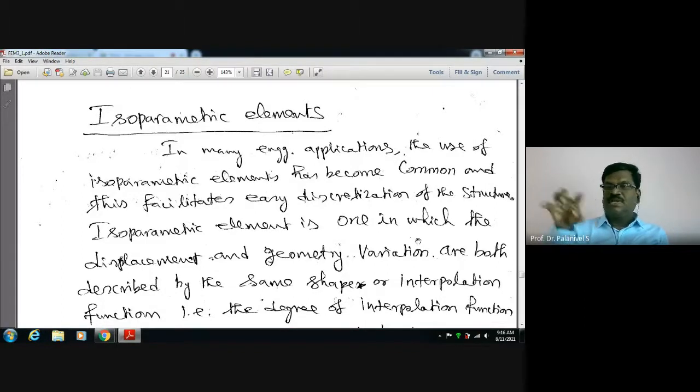For example, you take a triangular element, right? The nodes, you have three nodes, no? Say the displacement at node 1 is U1, V1. Because it is two-dimensional, we are resolving the displacement in some direction into its rectangular components. Node 2, you have U2, V2 displacement. At node 3, you have U3, V3. They are the nodal degrees of freedom, the nodal displacements.